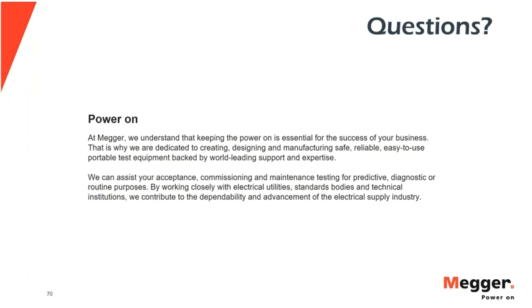0.5% is a suggested value for analysis if you do not have a historical reference. Then this is the only thing that you can say, well, if it is over 0.5, I need to investigate. It's not saying in any document that when you reach 0.5%, you need to scrap your transformer. So think about it. It's a suggested limit to start investigating and looking into more information if you do not have any historical values.